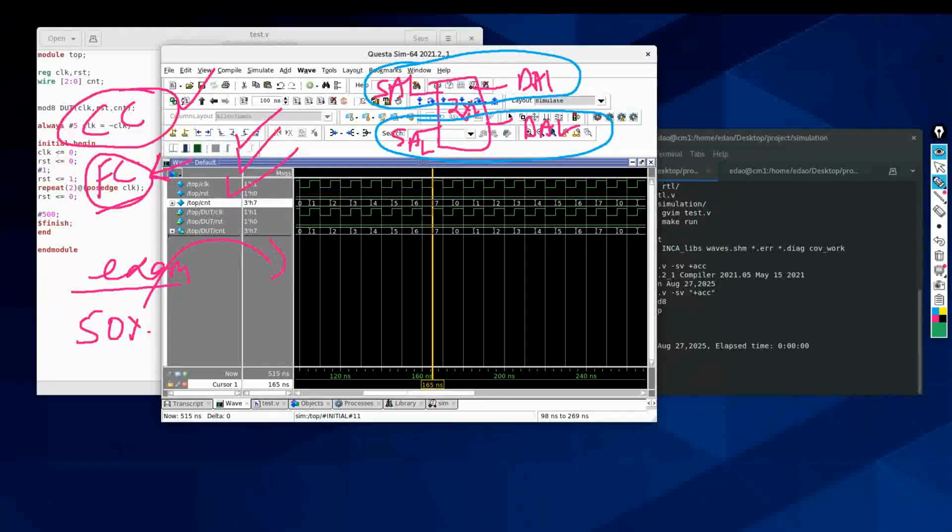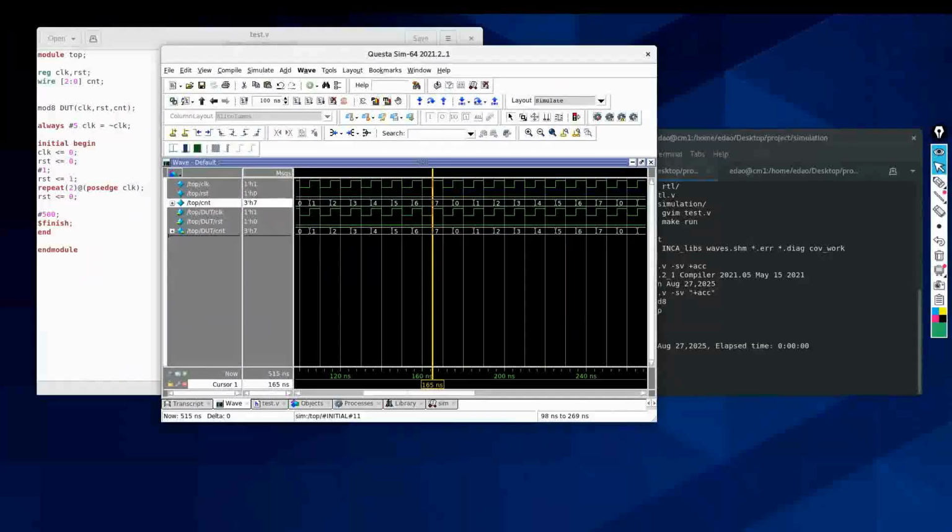You have to write coverage. There is one more path, source address 1 to destination address 2, and source address 2 to destination address 1. How do you know that you have not missed them? Because now the designs are so complex. So in order to give a sign off that yes, I am done with the verification, whatever RTL you have should go to the other stage, which is synthesis. We do coverage.